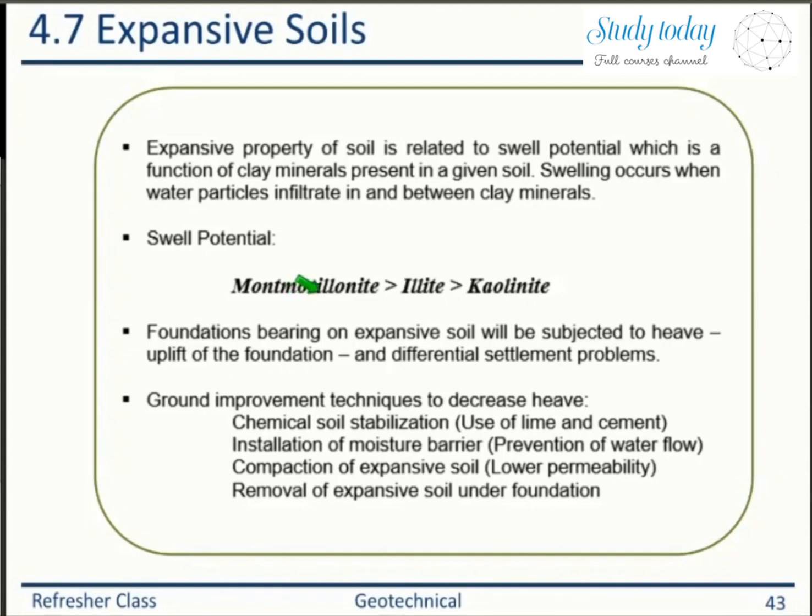And meantime, when the temperature is dry, water evaporates, everything will shrink, clay will shrink, so the foundations or roadway will move down. So this moving up and down is not suitable, right? Some of the clay soils expand, and the intensity of the expansion is dictated by the clay minerals. Clay with montmorillonite will expand the most, followed by the clay with illite, and followed by the kaolinite minerals. To prevent the settlements or expansion of the soil, ground improvement is needed.